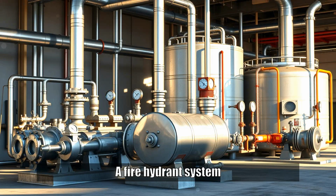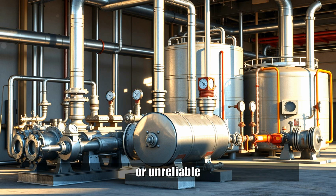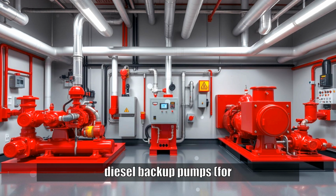A fire hydrant system is often supported by fire pumps and storage tanks, especially in industrial or remote installations where municipal supply is unavailable or unreliable. A dedicated hydrant pump room is designed with jockey pumps, for pressure maintenance, main electric pumps, for firefighting duty, and diesel backup pumps, for power failure scenarios.